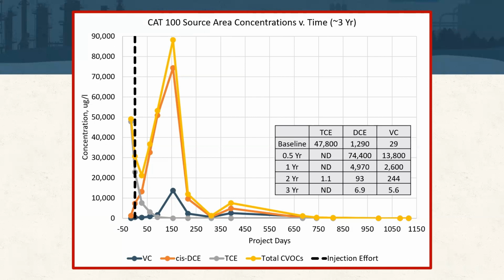And so you see here, starting at about 48, dealing with the TCE, the parent compound, is pretty easy. What is different for me, having worked on traditional ERD sites over the years, is that DCE generation is not unique. But how quickly that DCE and then the vinyl chloride did decrease, I think, is unique to this technology.